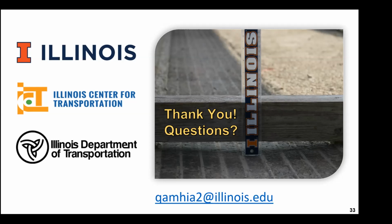So what we did in this test in particular is that we mostly had Quarry byproducts, or those sand-sized materials, tested in this project. So basically either that or mixed with some recycled materials. If you want to ask how they will contribute to the durability of other samples, like if they're mixed with other materials, they might actually, based on the idea that if those fine materials can react and over time contribute to the cementation of those layers, they will contribute to that.